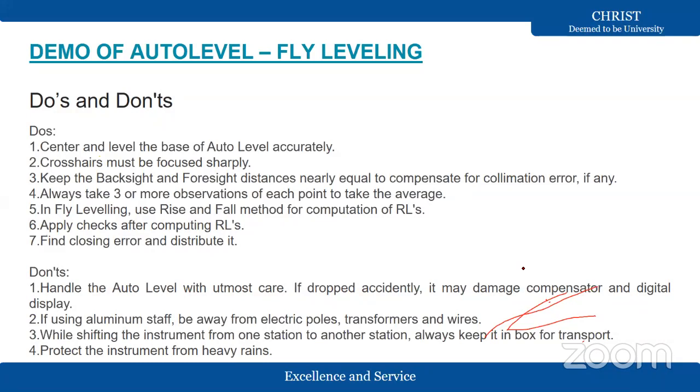So always you put it in a container, then you take the instrument. Once you fix the tripod, then only you have to fix the leveling instrument. Whenever you are transferring the instrument, you have to remove it from the tripod, then carefully keep it in a box, then fix it again in the other position.